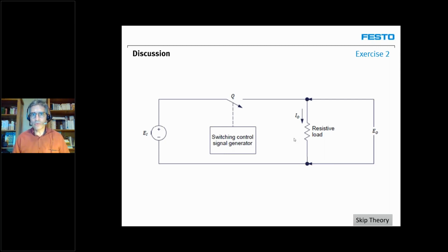hundreds of amperes flow through. So this allowed us to start doing not electronics, but power electronics, so controlling the large currents and voltages using transistors. At the same time, these IGBTs developed in parallel with thyristors, which were meant for high power implementations. But nowadays, the power transistors are so good that they are quickly replacing all the thyristor installations that were there before. So as you know, a transistor is simply a switch that we can control electronically to let current go through or not.